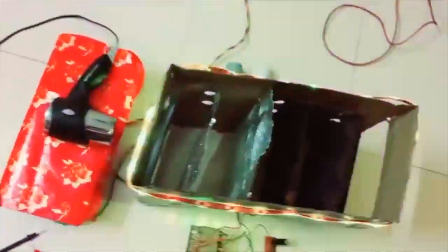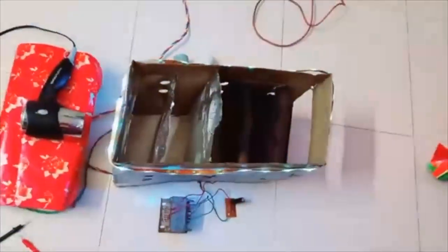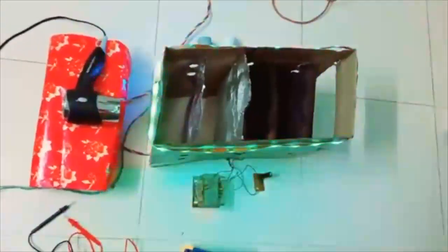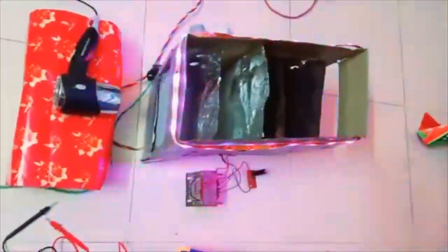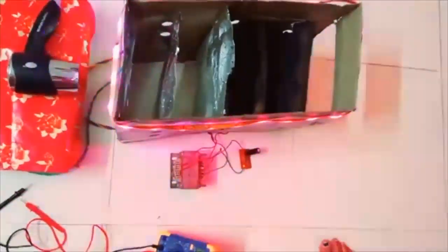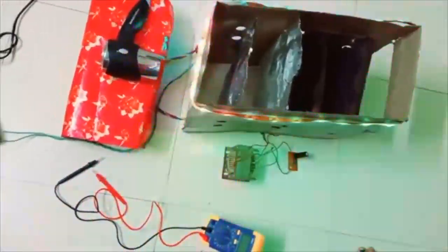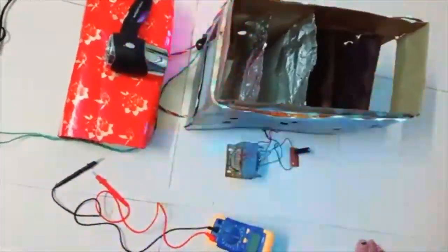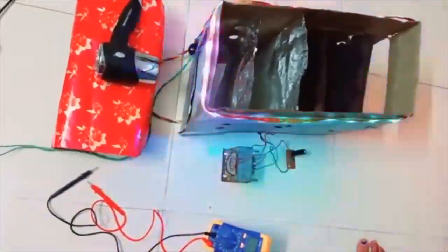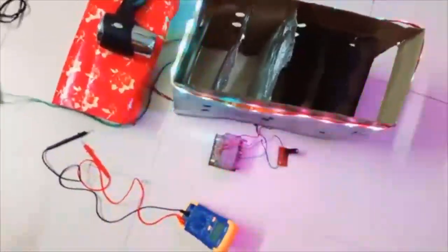First, at the initial stage we have a metal plate which is also electrically charged. That will capture most of the carbon particles, soot particles, or any big chunks. Then we have two electrical plates. These electrical plates are highly charged. They will be charged by this transformer and the capacitor. As we have studied in chemistry, if charged particles come in contact with an electrical field, they lose their charge and get coagulated. It is the same principle used by chimneys. We used the same concept to capture the carbon in the air.